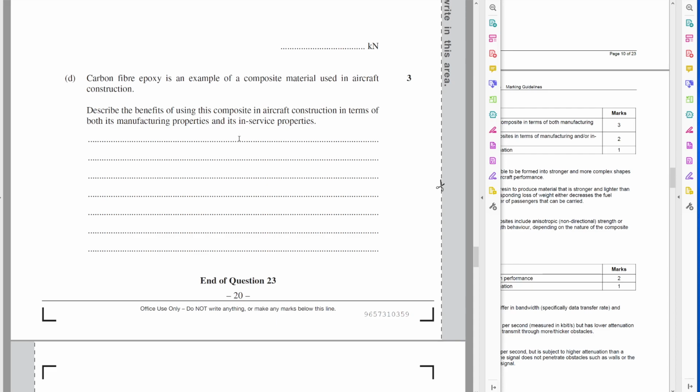By the way, Real Engineering, the Irish guy, he has a video that talks about why the Dreamliner windows are so big. And he says that the reason for that is because we have massive changes in pressure on planes. And because they go through these massive changes, the plane is effectively growing and shrinking all the time. And that puts enormous load on the plane, especially at the points where there are openings in the plane, which is where the windows are. By using carbon fiber, its fatigue resistance allows us to have larger openings without compromising the strength of the hull.